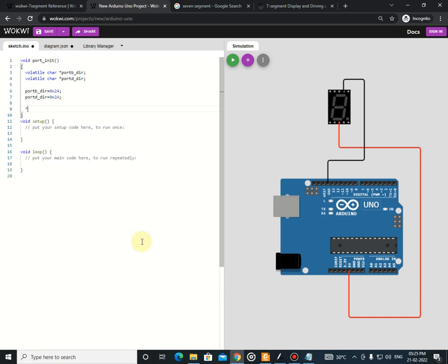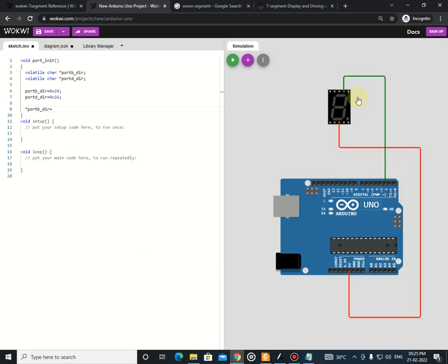Next we want to denote our pins, whether we are going to use these port pins as input or output. So we want to write values in the register to indicate that we are using them as output. So I am making the pins that we are going to use. First we need to connect our 7 segment, then we can write the program.